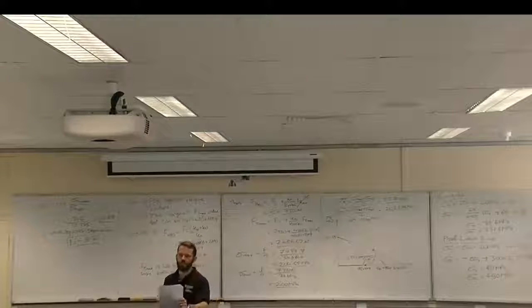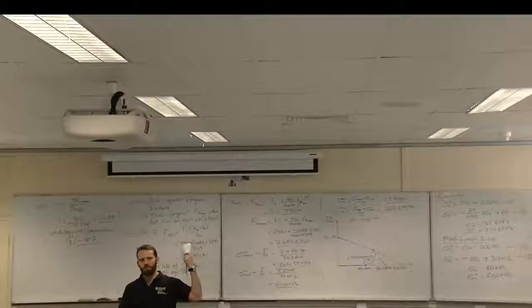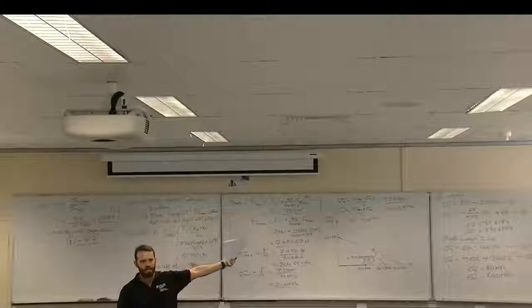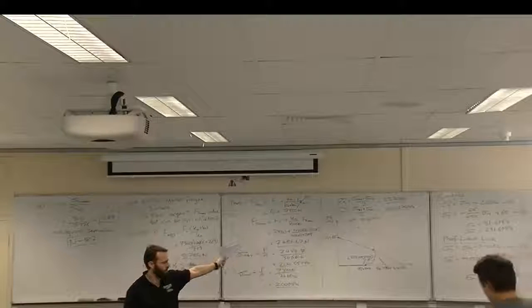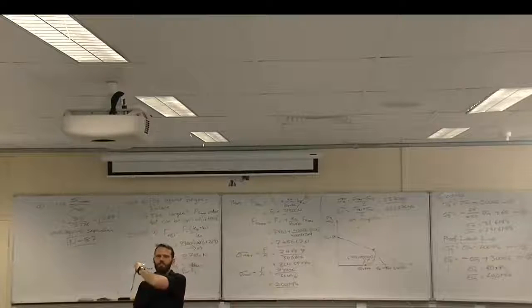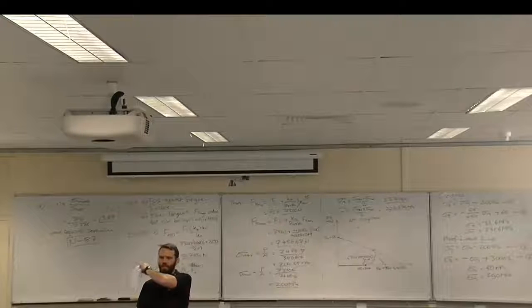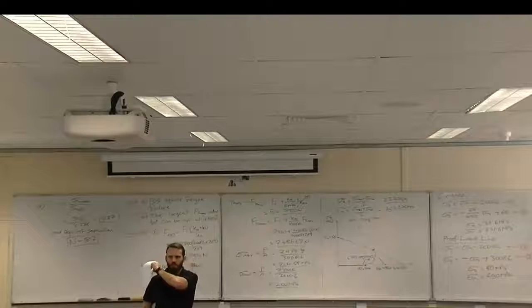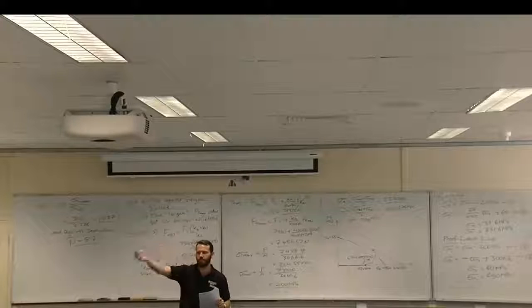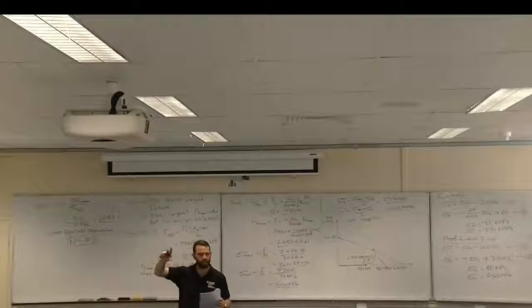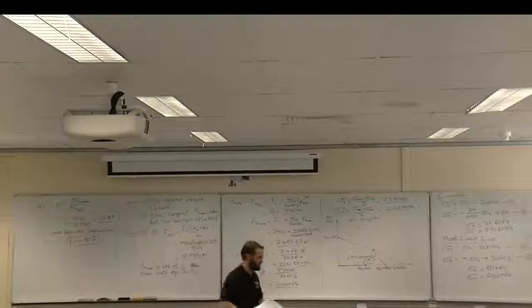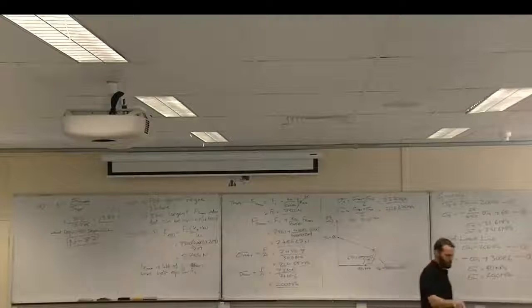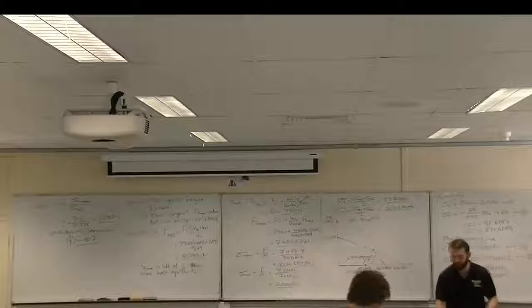Sorry, that was what I was trying to say. So you calculate the maximum force of the bolt just by rearranging that equation, multiplied by A and whatnot, and then you need to calculate the externally applied load that's allowable. And that depends on whether you're to the left or the right of that separation. So that was the last one. But that's the numbers.